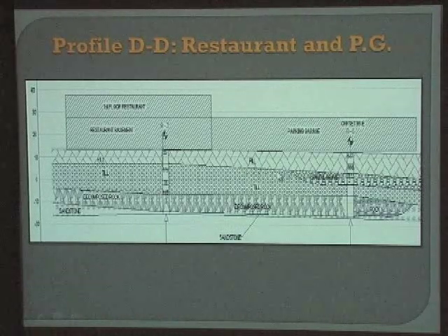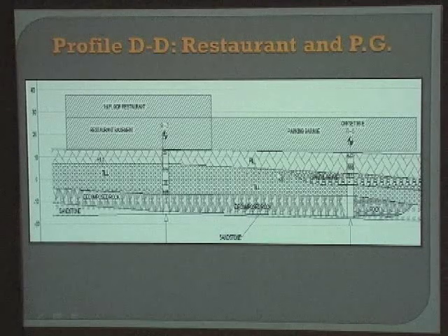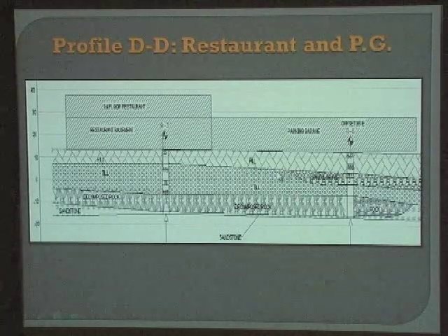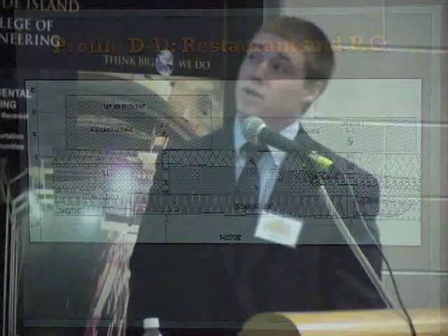Once we do this, we'll have a pre-existing fill layer of about 8 feet with blow counts of 31, which describes the soil as a dense soil. Below this, we'll have 8 to 11 feet of very dense till with blow counts up to 150. Beneath that, we have a layer of decomposed rock, and then followed by sandstone.